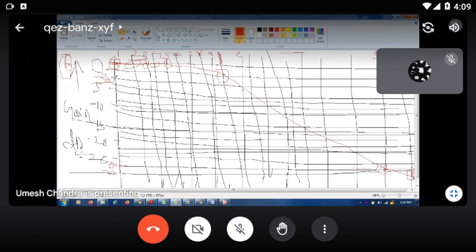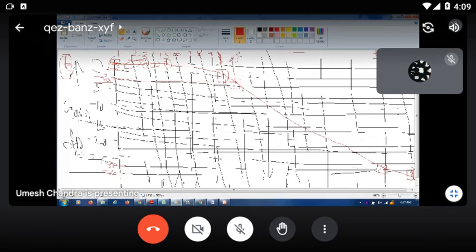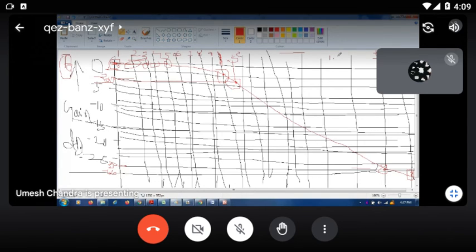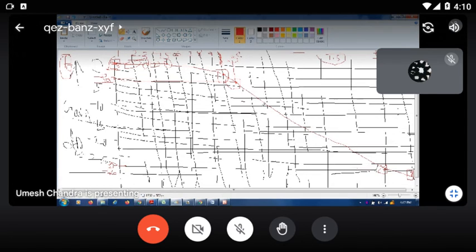At minus 3 dB, you draw a line, and where it touches, that is your cutoff frequency. Suppose this line, this is the cutoff frequency. This is 1 kilohertz, and between 1 and 2 kilohertz, suppose here is 1.5, and your cutoff frequency is 1.5 kilohertz. This is your low pass filter observation graph. This is the low pass filter.